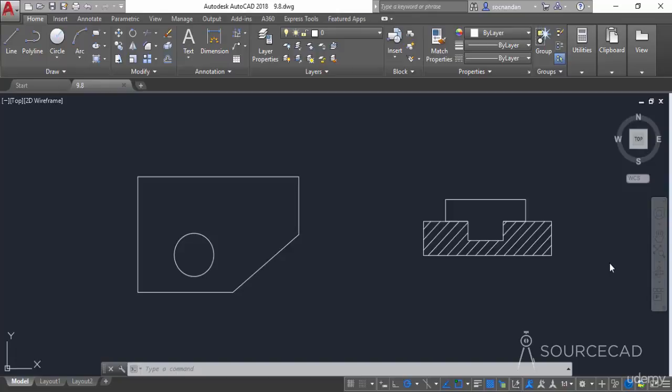In this video, I will tell you about adding feature control frames in our AutoCAD drawings. The feature control frames are added for representing tolerances and most of the geometric dimensioning and tolerancing information. So in order to add the feature control frame containing all of the GD&T symbols, you need to once again go to the Annotate tab.